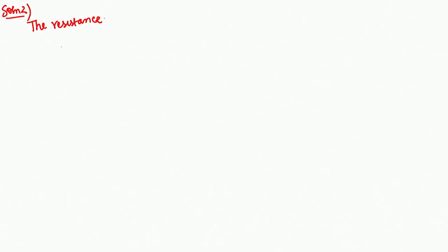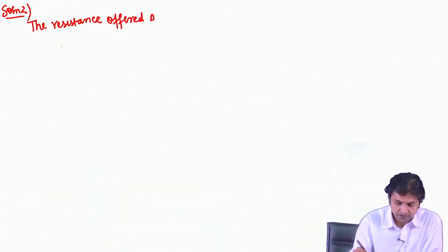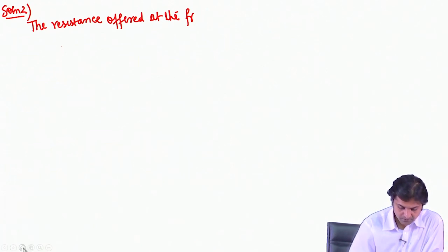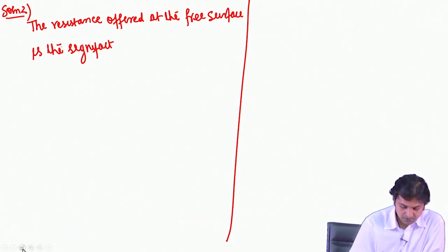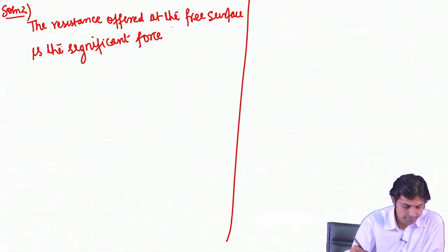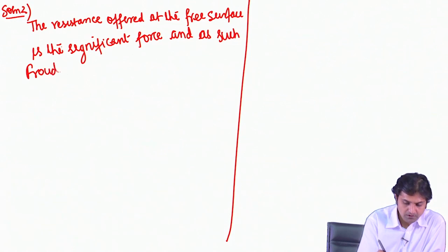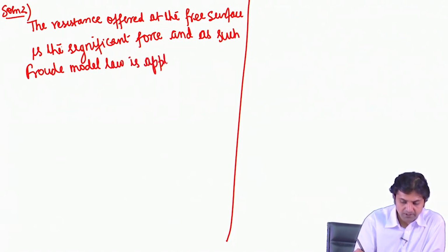So, the resistance offered at the free surface is the significant force and as such Froude model law is applicable.